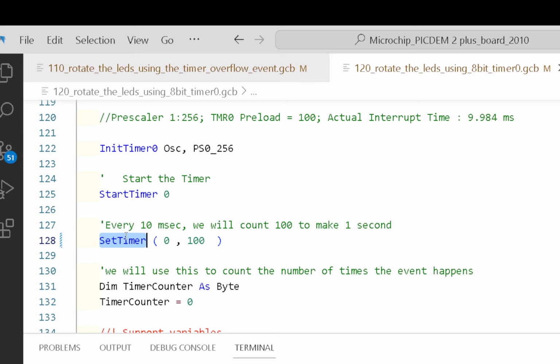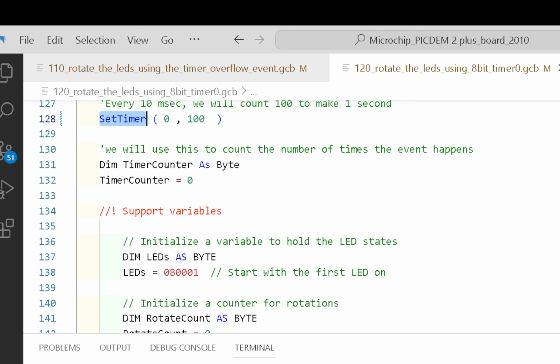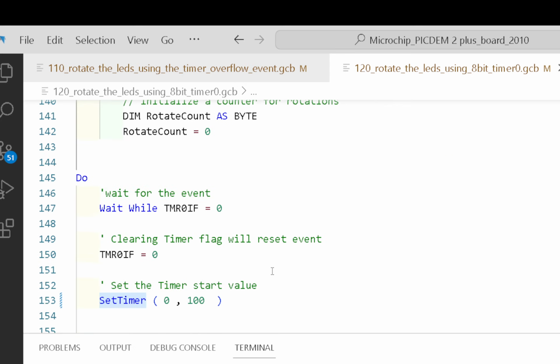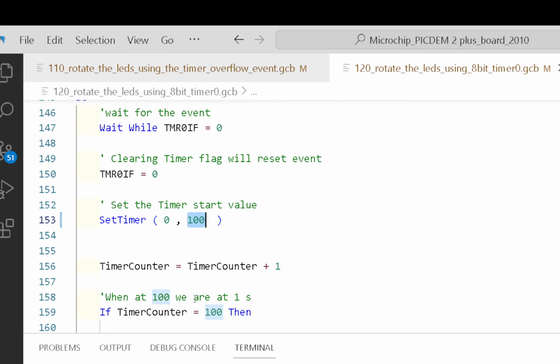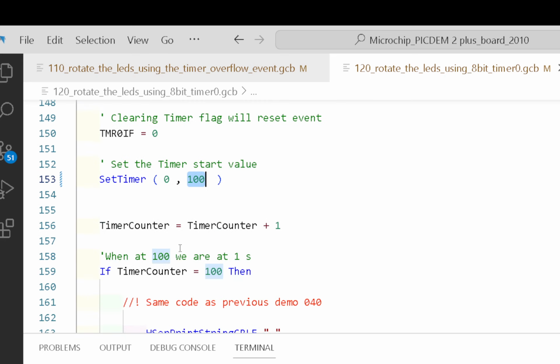So, how do I get around this problem of getting bigger times on these legacy chips? I mean, this is counting up, 100 of these so I can make a second. It is hard, and that's the difference between these legacy chips and the newer chips. They have a post scaler as well as a pre-scaler, so you can stretch the clock further. We cannot do that on these. We only have one scaler to use.